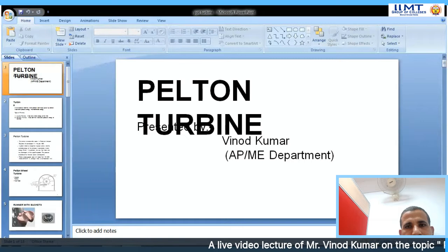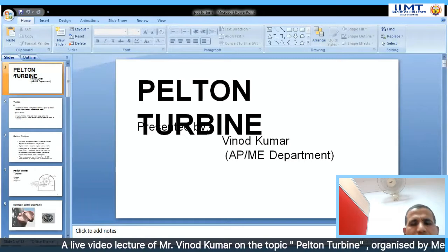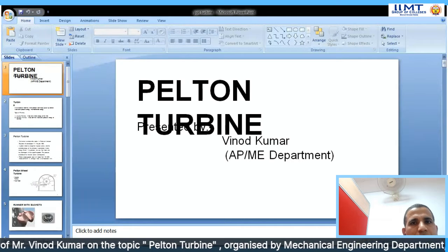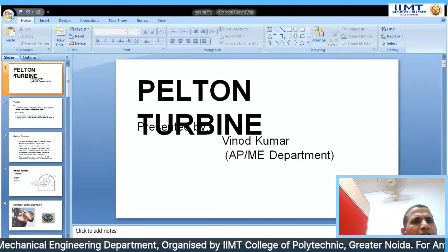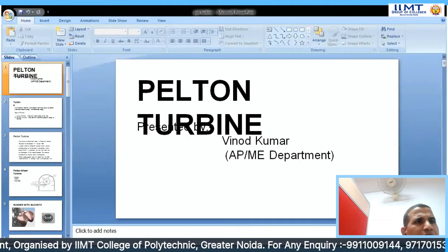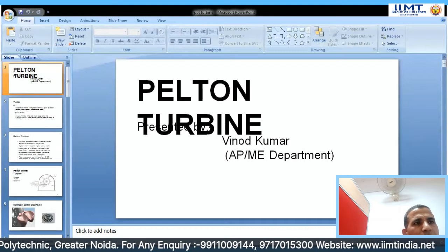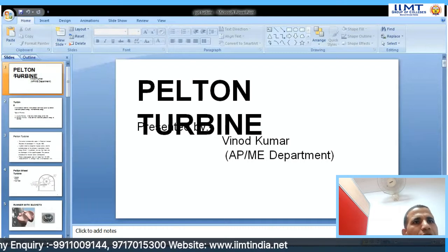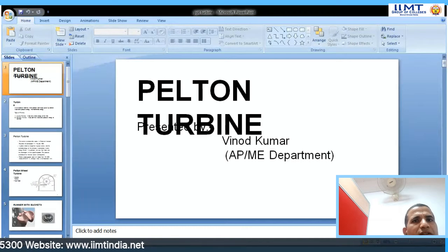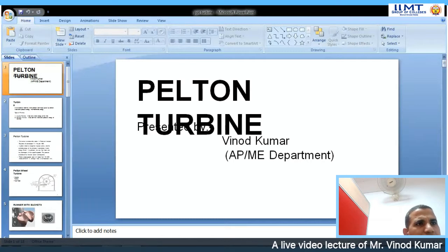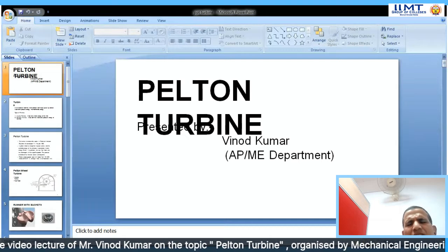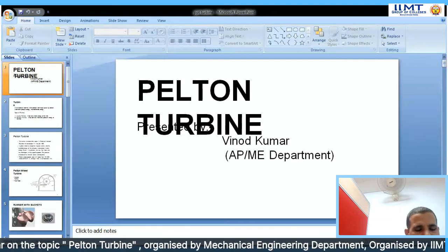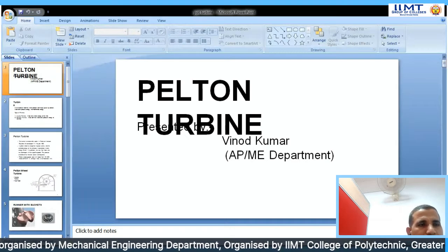Then comes the runner. The runner is what rotates all the time in the Pelton wheel turbine. The runner is nothing but the wheel. The runner of a Pelton wheel consists of a circular disc fixed on a horizontal shaft. The shaft is horizontal and the runner is vertical. On the periphery of the runner, a number of buckets are fixed at uniform distance. Then come the buckets. A bucket is a hemispherical cup or bowl with a divider at the center. The divider is also known as the splitter, where the water gets split into two halves.